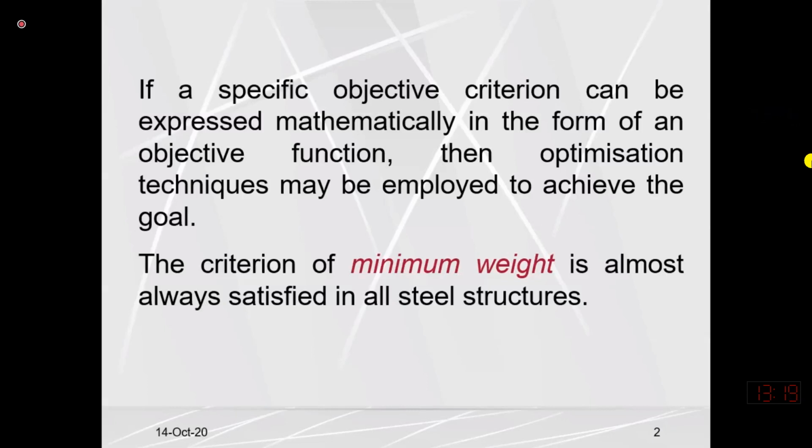So we require some extra stiffness. It means that our structural member will be over-strengthened or maybe a little bit uneconomical. A little bit uneconomical means that here our first objective or requirement is not the economy. Our first objective is the deflection control limit. So if we want to control the deflection, we need a larger section because deflection can be controlled by the moment of inertia.